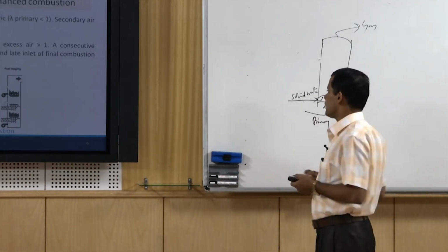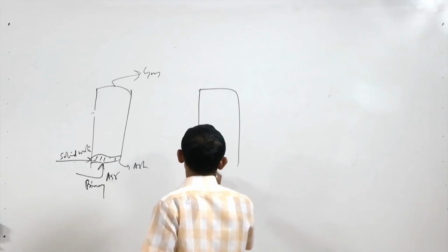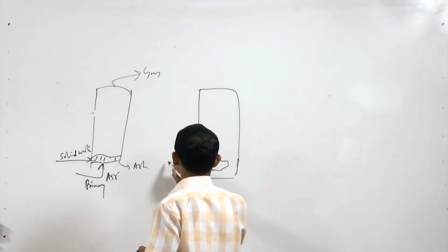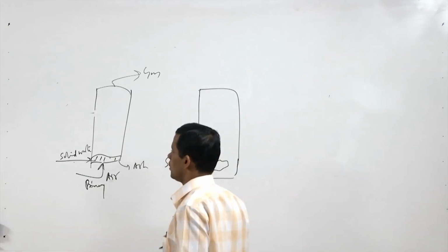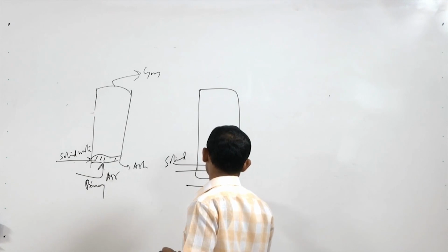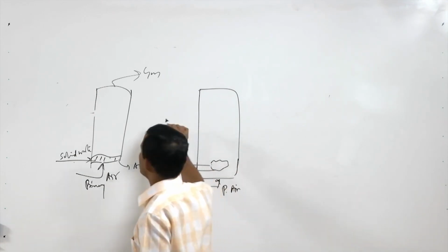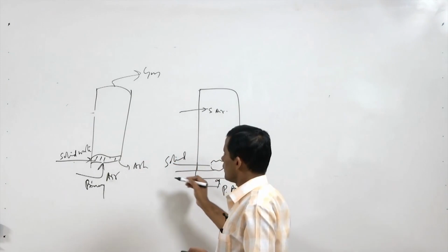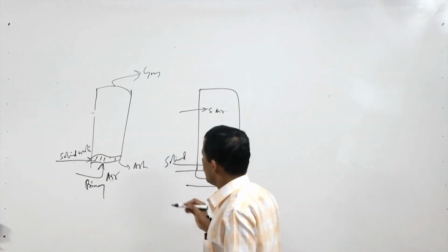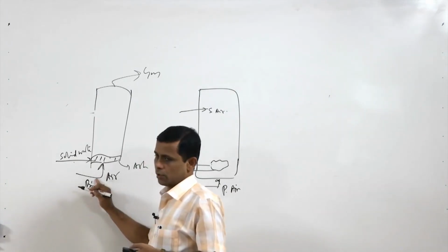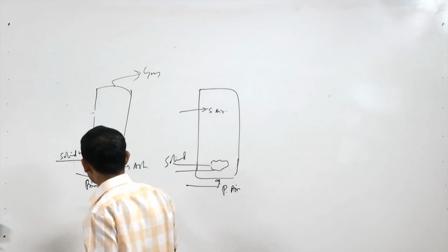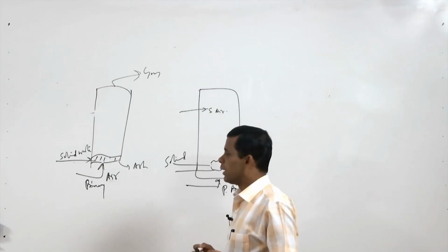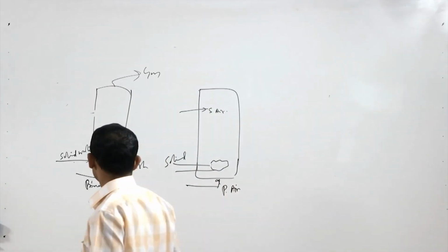Now, staging, say we are going for air staging. So, air staging means we are putting here solid waste, we are putting here air, primary air, and then we are putting here secondary air. How does this process change? In the conventional case we need excess oxygen, very high, or more air is required in comparison to the stoichiometric ratio. Here the air requirement will be lesser than in this case, the excess air requirement, and the quality will also be good.